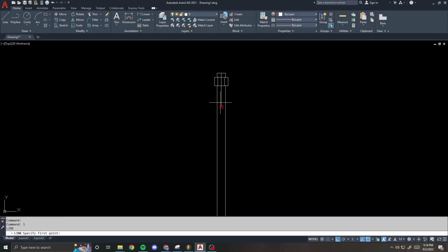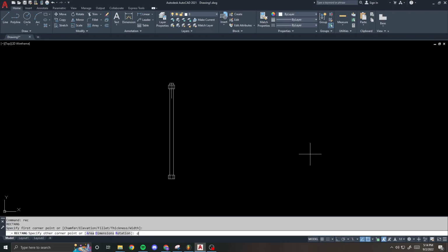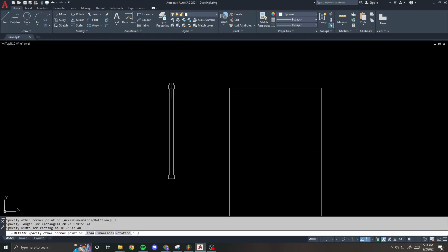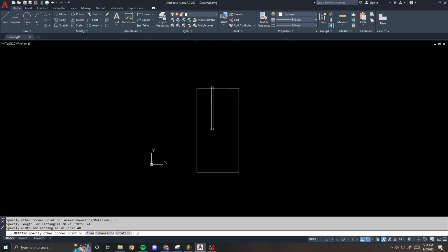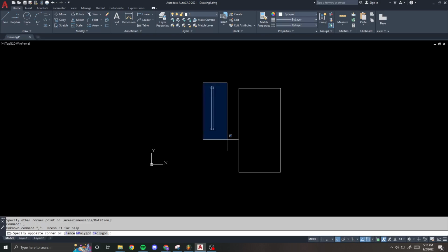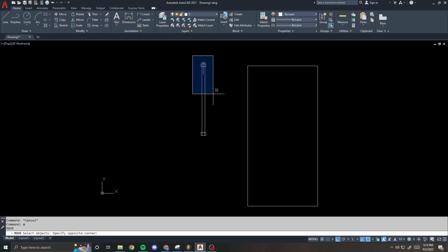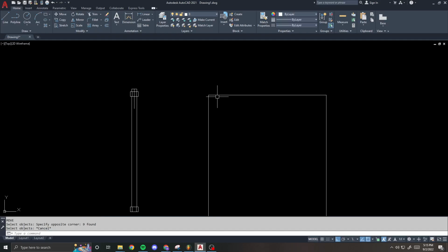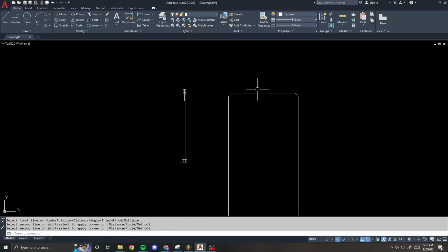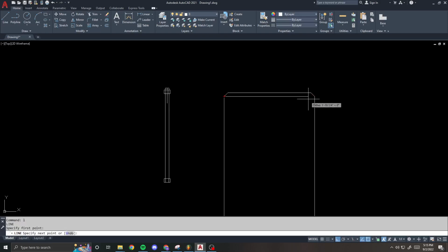Just as a quick reference, let's say I've got a pedestal and it's 24 inches by 48 inches. This is my pedestal. Okay. Come on, click. There we go. All right. And I want to place this anchor bolt. And let's put a little grout. Let's do a chamfer with a 1-inch grout. Okay, there's our grout pad.